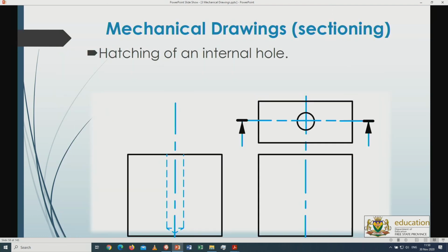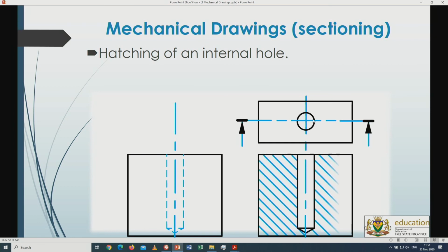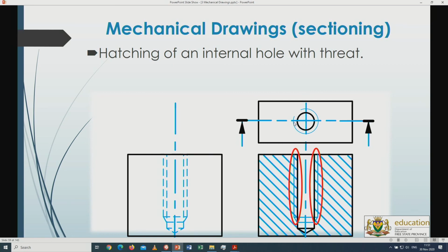So if I've got my machine part over here, now remember this is the top view, I need to drill a hole inside here. It means that this will be smaller than diameter if I drill this whole part over here. Then diameter will be from there to there. What's the distance in there? It's 0.1 of diameter, and the distance from there to there is also 0.1 of diameter, the same over here and on that side. So there we go. Hatching must go right through towards the hole like we have shown you there.